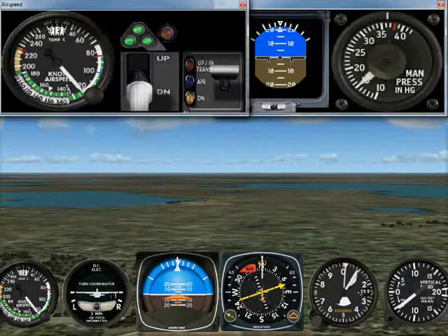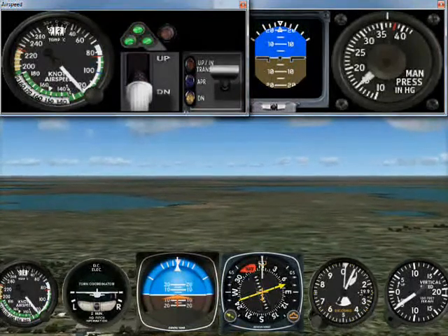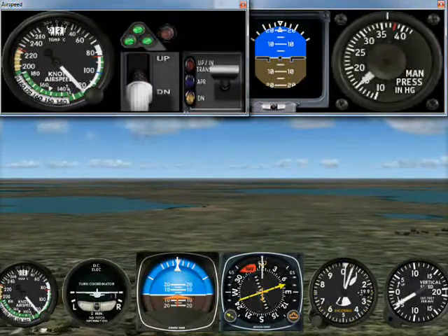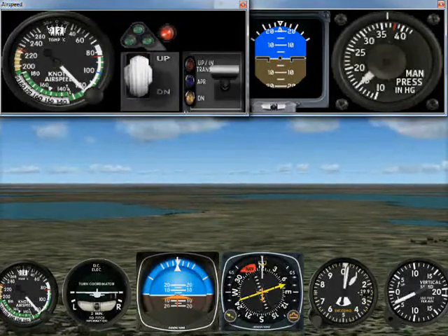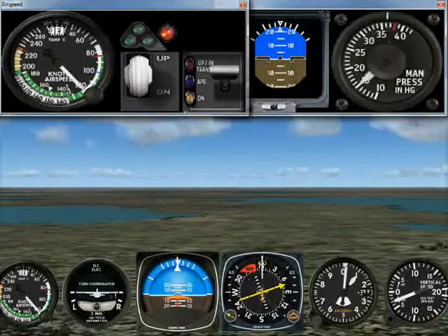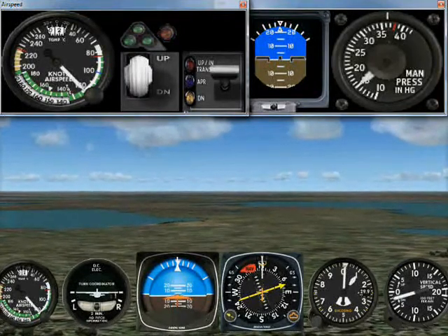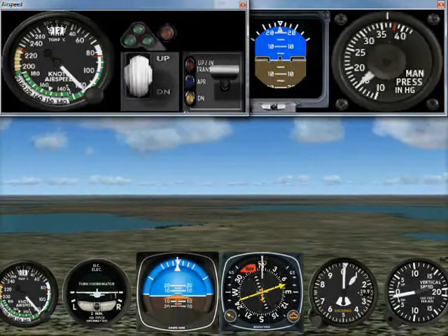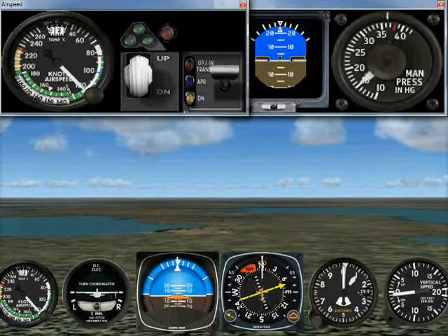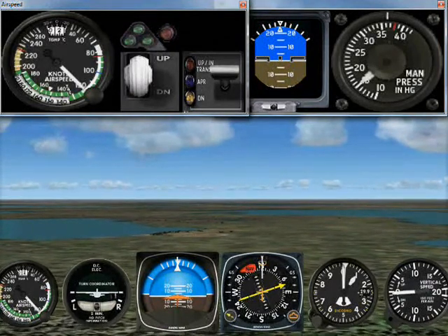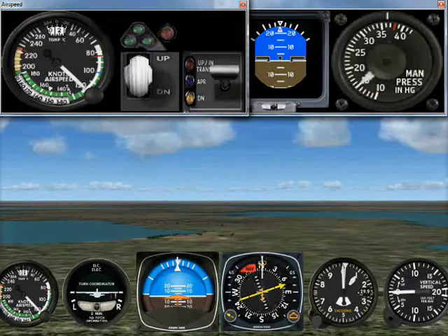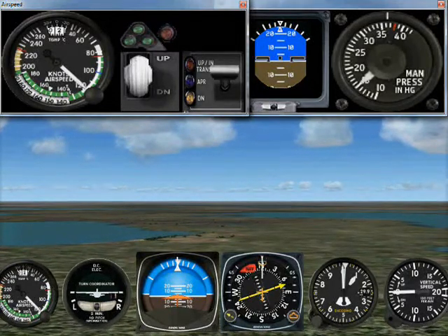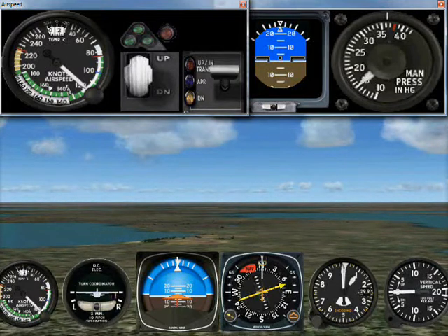We will level off at 1,000 feet to determine the downwind leg settings. Leveling off, we raise the gear and watch the airspeed. If the speed stabilizes at 120 knots or greater, then 15 inches of manifold pressure would be our downwind leg power setting. This was the case for the previous jet visual approach, which used the same power setting for the downwind leg and the final descent.